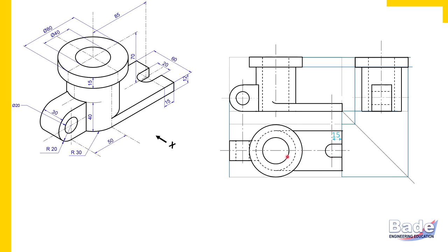A hole has a closed boundary, a circular hole here. Also watch the hole in the U-shaped block. It has a closed boundary, but this is a slot. Its opening doesn't have a closed boundary. Watch here at the right end, between the top corners, there are no edges. So we'll have to trim that portion. Watch here. So this is how we have completed the U-shaped slot in the top view.